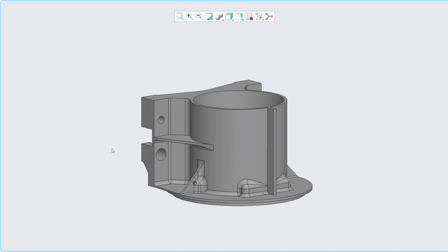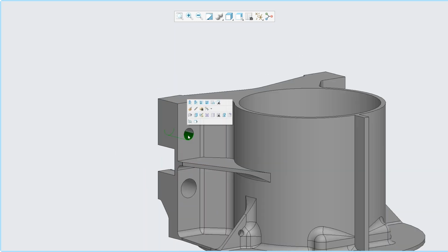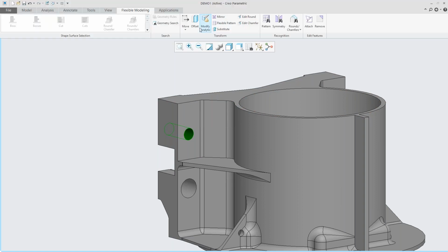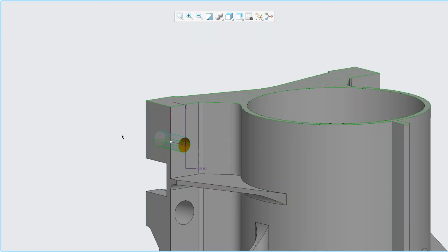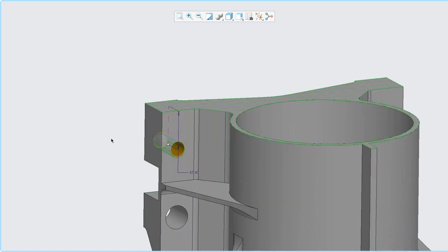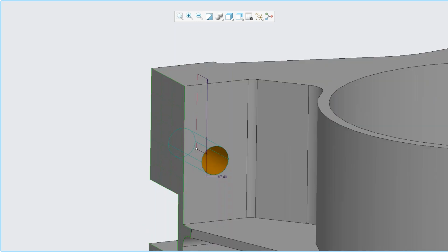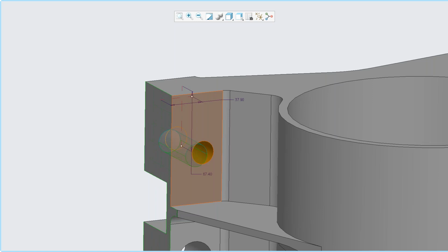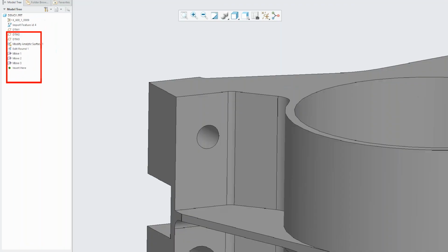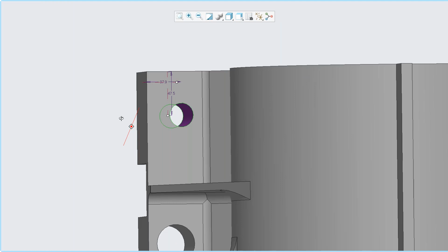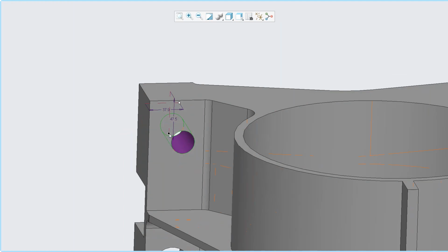You could go and select that geometry additionally, or you could say, I would like to transform this, for example. I want to select that cut and do a move on that one by dimension. You could absolutely do that, and say, okay, I want to add a dimension between that and this one, and look at that, it created a dimension from that surface. So you're essentially featureizing it as required. Now, what about the linear dimension in the other direction? I could always add a second dimension and say, how about from here to here? So really, now the question is, why would you need a feature? I understand that I don't have a feature called hole here to do my edit or edit definition, but I do have the move, which allows me to dimension. I could just say, okay, these are my linear dimensions, right?